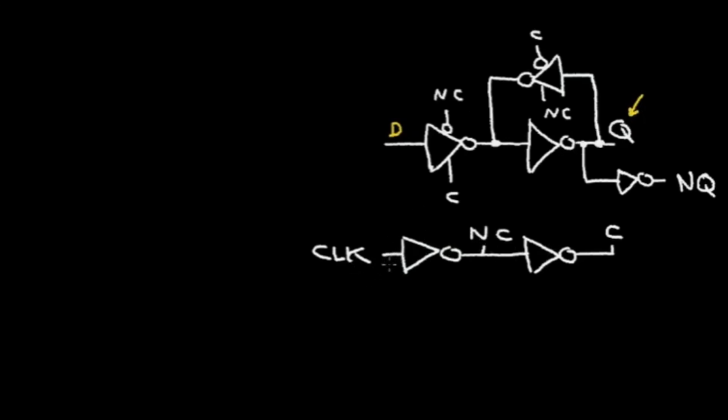So for example, when the clock signal is high, this first tri-state driver is in the inverter mode. So it allows the data to transfer into this latching circuit.